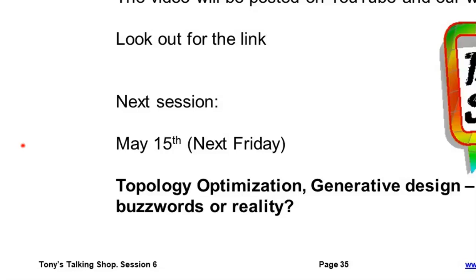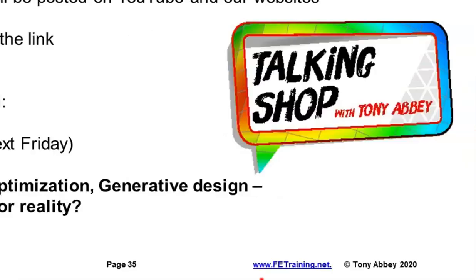If we're doing a hand calculation, there will be a nominal stress times KT, which we look up in a textbook or some other method, and so we get our peak stress from a hand calculation. From an FE analysis, it's the peak stress that we get directly. So it's the elastic stress amplitude coming from our FE analysis.